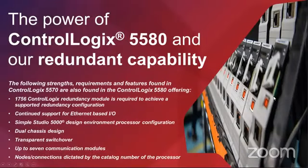Again, as of the August timeframe, with the release of V33, we will be adding the 5580 or L8 processor as a redundant option. It will follow suit very similar to the L7 architecture design. So the way that we handle the two separate chassis, the communication modules, the manner in which we do the switchover, the RM2 modules, which are the redundancy modules for ControlLogix, those stay the same. So it is still the 1756 RM2.